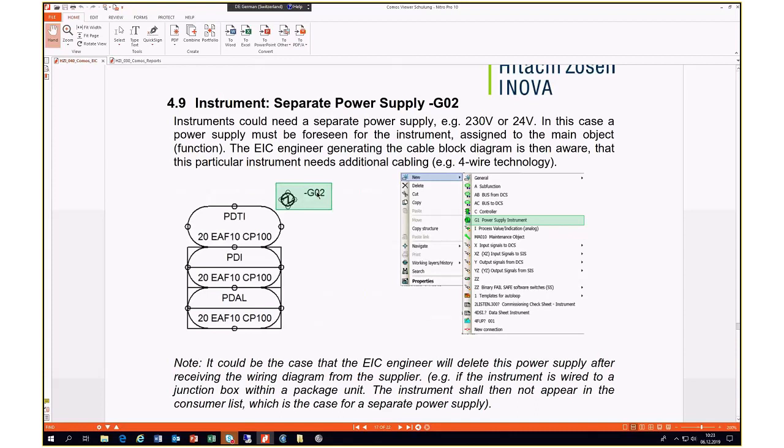And you have also these power supplies. Again, that's just basically a sub thing, that is inserted the normal way with the new inserting power supply. That's like I explained. That's something you have to sort of understand, because often they're grouped together, right? You'll have instruments and they'll be powered from one cabinet over here or whatever. And then it's not common to have a power supply for each instrument. It depends on the location, right? So if the instrument's way up high somewhere and it's far away, then it might have to have its own power supply. I don't know.